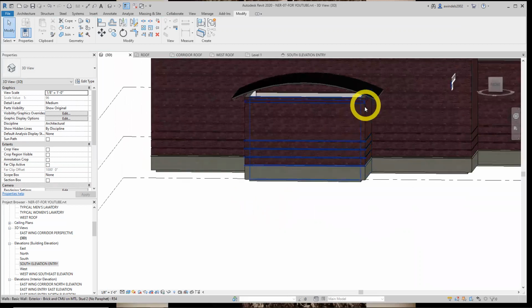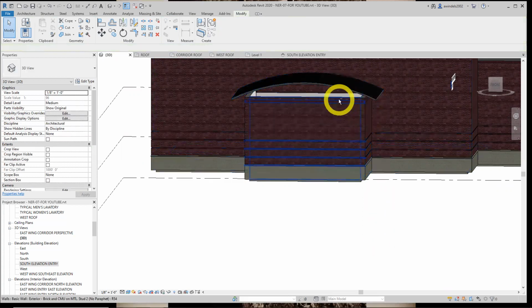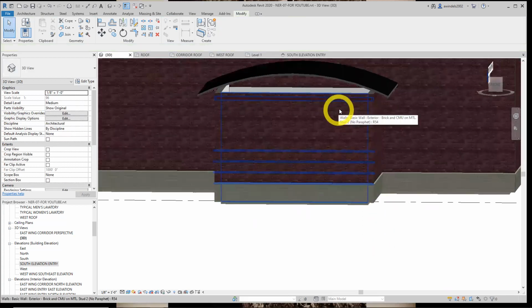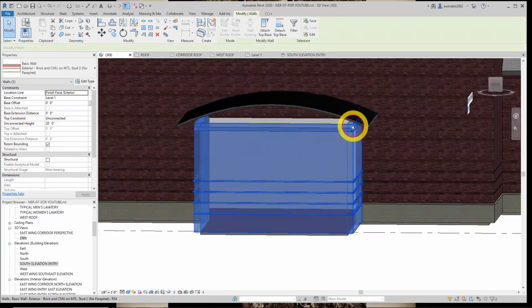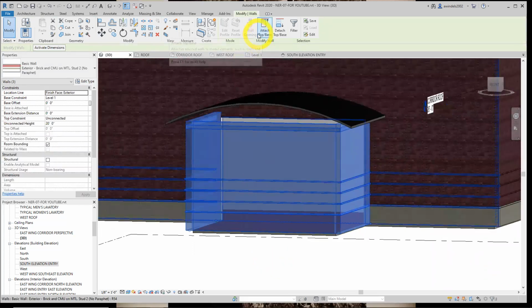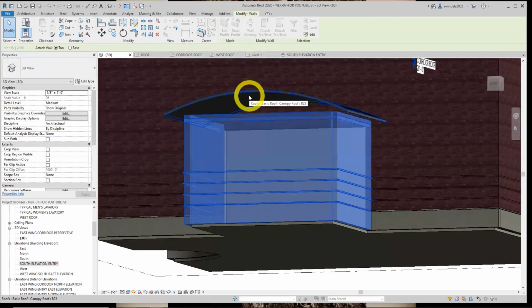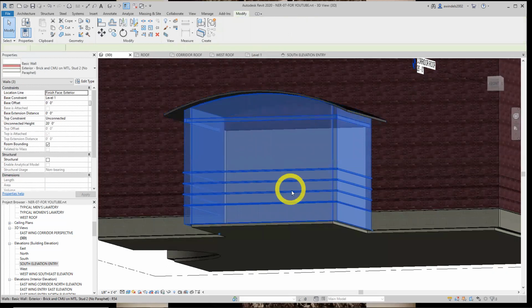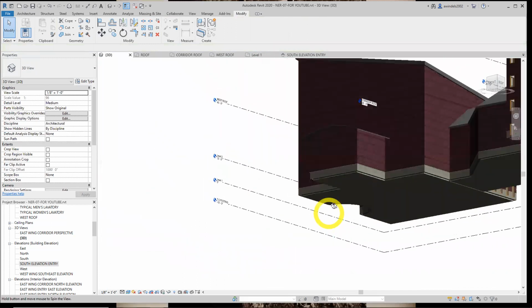With that, last step is what we just did on our last job, is to extend our flat walls smartly up to our new roof. Let's zoom in here a little. All three are picked. And zoom under so I can have something to pick to, attach top base, base of the roof. There they go. There we are.